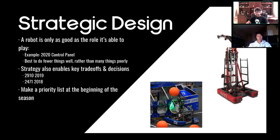They had this lift system, but they also had this arm that was able to reach around backwards, instead of just having a simple wrist that could only reach the minimum amount to hold the mechanism inside of your frame perimeter. What that enabled them to do was reach over the back of their robot, and during auto, that gave them a huge advantage, and they were one of 3 teams to consistently hit 4 cubes in autonomous in 2018.